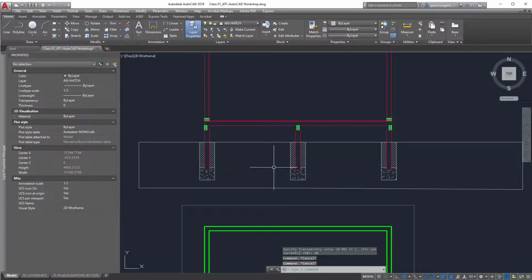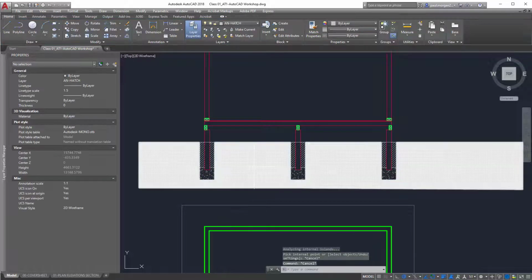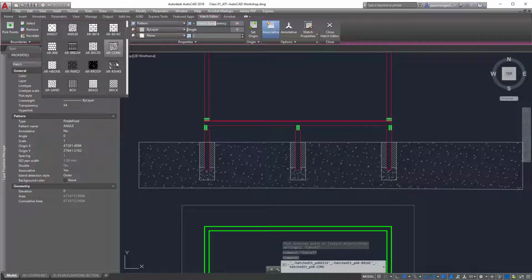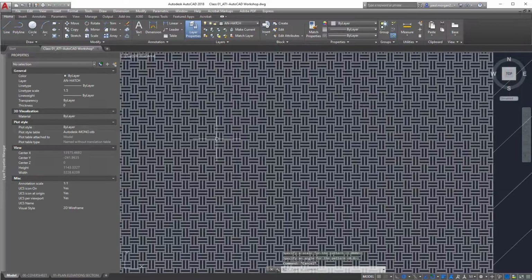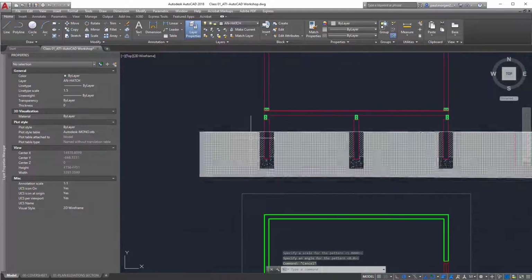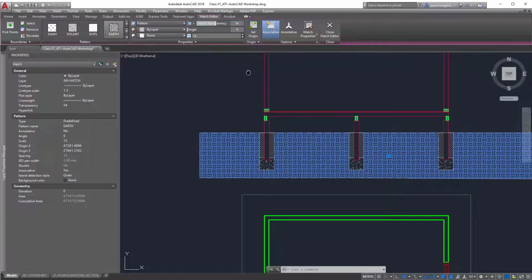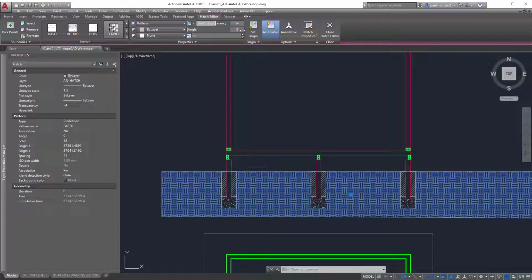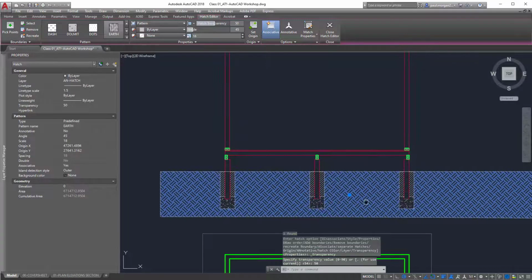And finally, the earth hatch. So hatch, click, escape. Now we're ready for our earth hatch. So I'll click on this, go to my drop down box, find earth, there it is there. At the moment, it's extremely small, as you can see as you zoom in on it. So we'll make this bigger. I'll make the size maybe 15. Maybe a little bit bigger, 18. And I'll turn the angle to 45 degrees. And the transparency, I'll make 50.